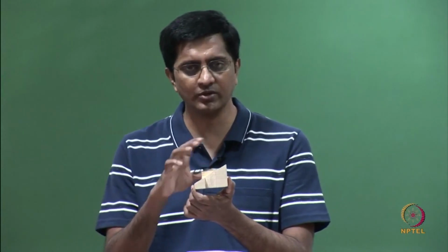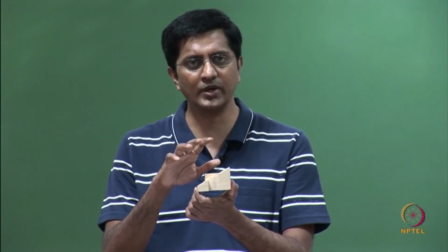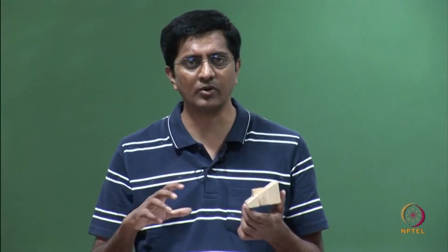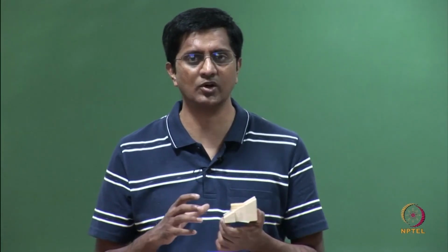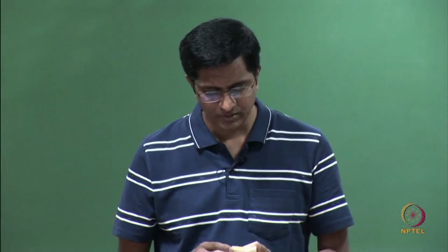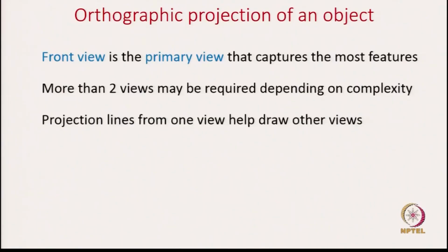But in this lecture we will only be focusing on basic views, and we will be looking at 3 different views such that that should be enough for most of the engineering objects, at least, that we use in practice. As I already mentioned, we may need more than 2 views depending on the complexity. And lastly, the projection lines from one view will help us draw the other views.